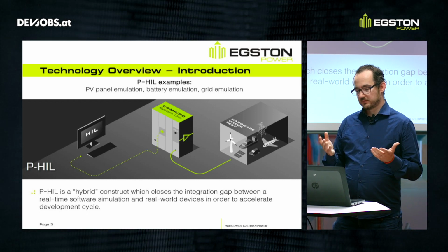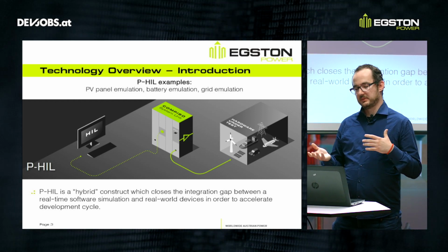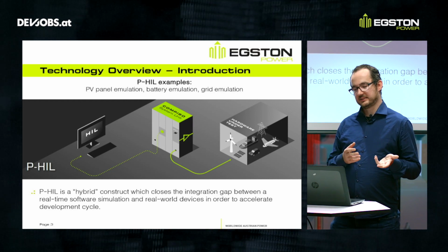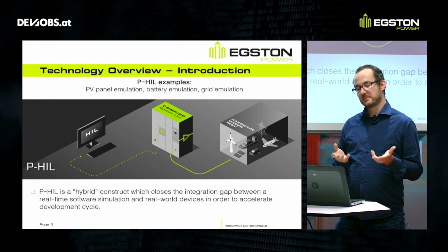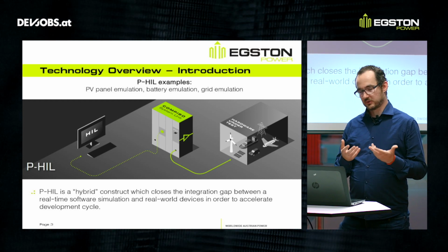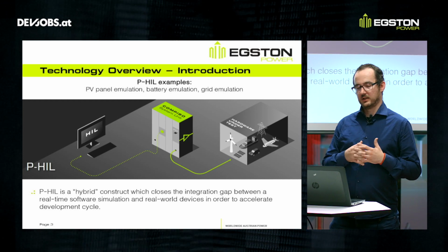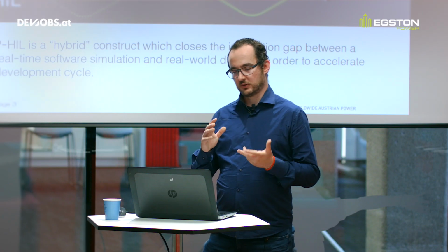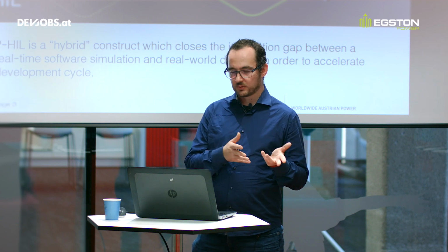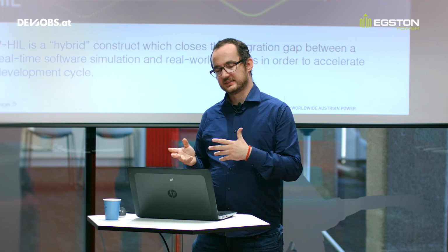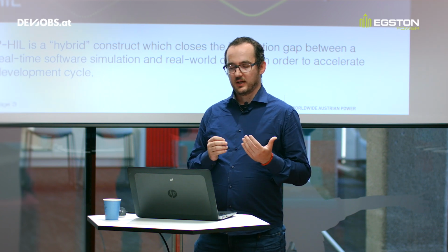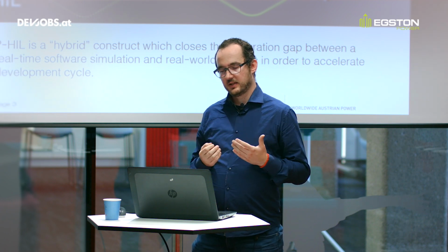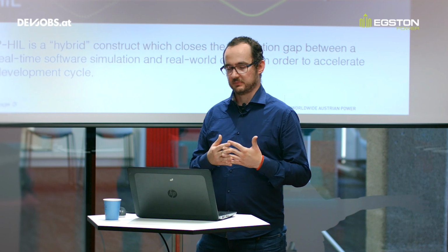That is maybe one of the best cases to show that by means of emulation we can emulate both DC and AC use cases with the same amplifier, which is of course an added value to the system like that. Usually many systems which go in this direction support only DC or only AC, or they are limited to one single energy flow direction, meaning that they are not 4-quadrant, but rather 2-quadrant amplifiers.